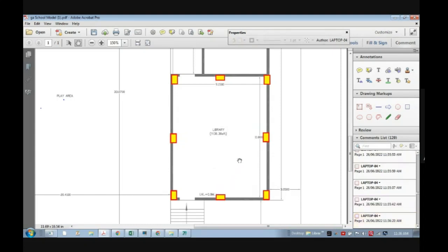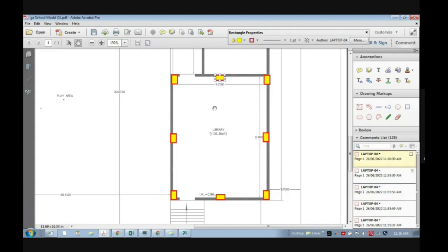Okay, now what will we do with this? Sir, we will give beams here. So the beam span will be 9 meters. So either one choice is, can you provide here like this? See, as a first instance, a structural person will do the easiest thing first.